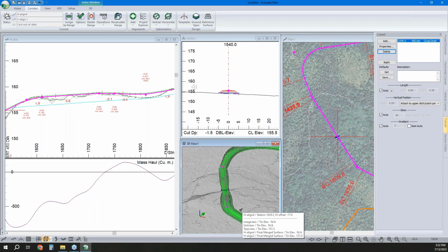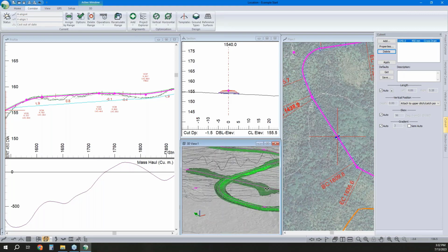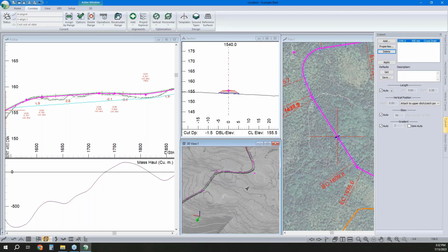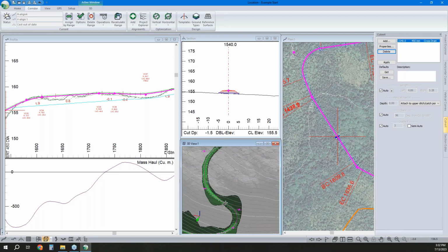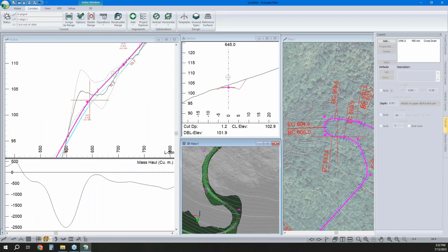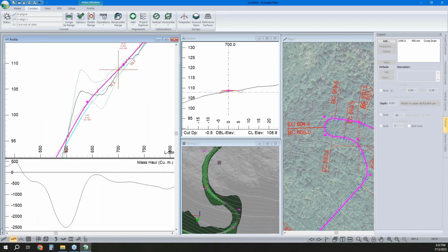And then the next thing on our list, and I'm circling back to stuff that we've already covered, but I said that most of the time we want to have our road crowned to move the water off to the side. That isn't always the case. And sometimes, rather than having the road split front load either side, it's beneficial to have an insloped or outsloped road.